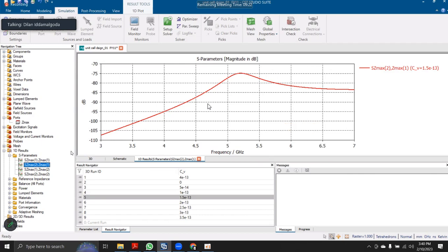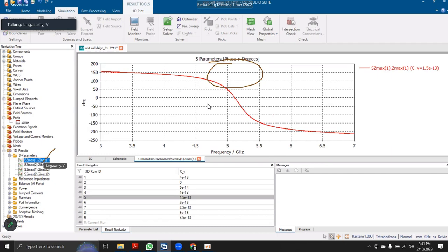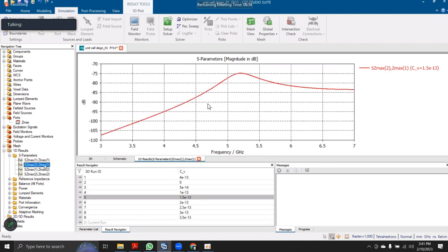What is better for reflectarrays? Both you have to check basically. Here the cross polarization is actually very, very good, -75 and low. There is no coupling between these two, that's why you are getting this. And if you check here, that is something you have to check, what degree you are expecting, all that stuff. Okay, that's it.